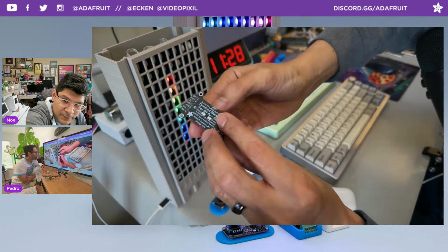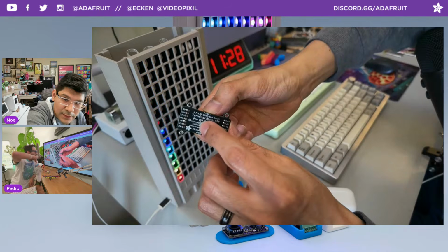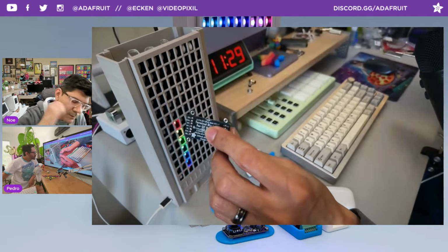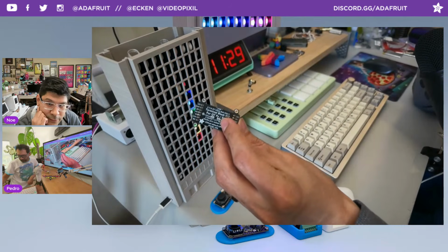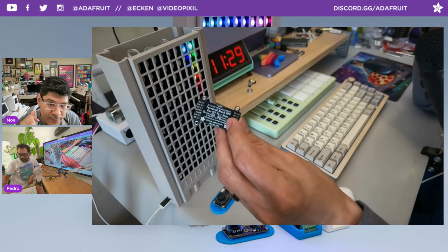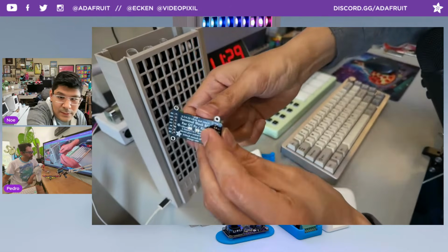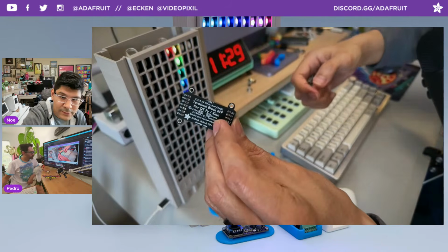What else about this board? Now that I actually have it, you can solder this jumper to do a 500 milliamp LiPo charging rate, so you can charge your batteries faster. It defaults to 250 milliamps, and then you can disable the LiPo charging here if you cut this trace so that you can use alkaline batteries.